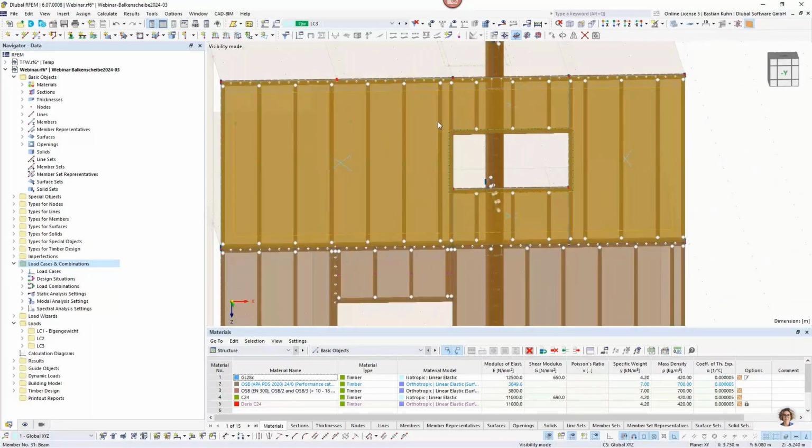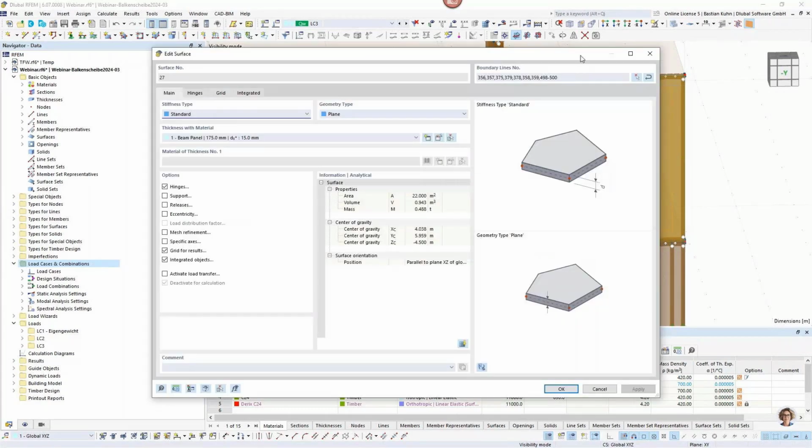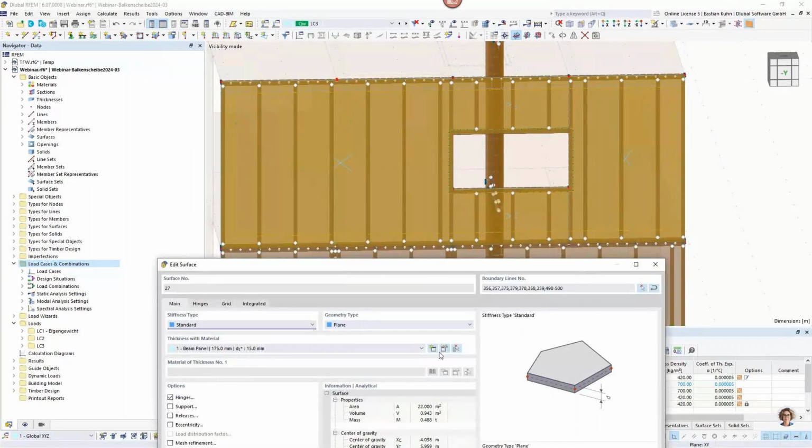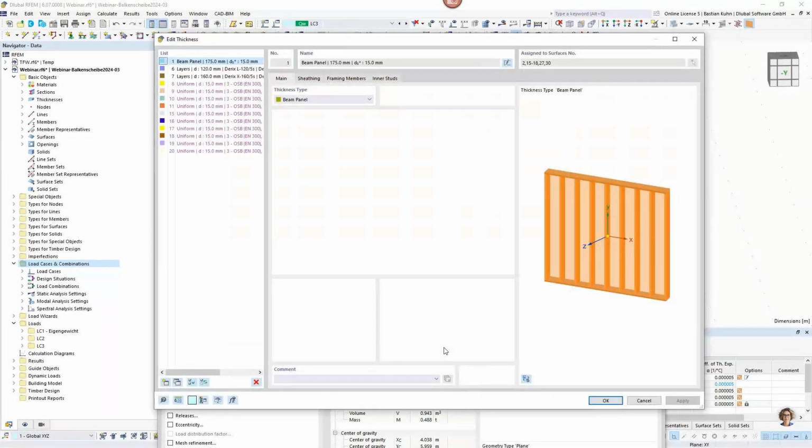We see that now the distribution of the beams and the posts is quite good. We would calculate the opening, and it kept our spacings of 625 millimeters in between, and here we have a middle value of 100 millimeter left, and this is also good because we can still get insulation into it here. But yeah, I said it. What I wanted to show you is what this special selection does in here.